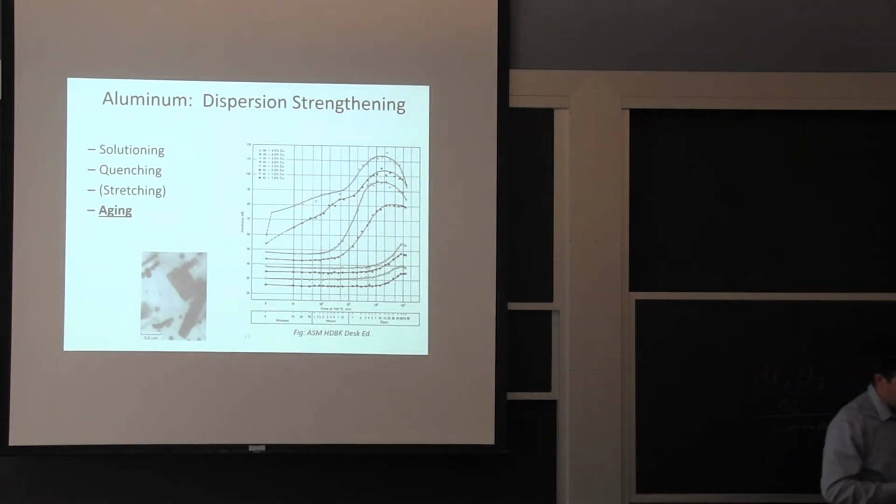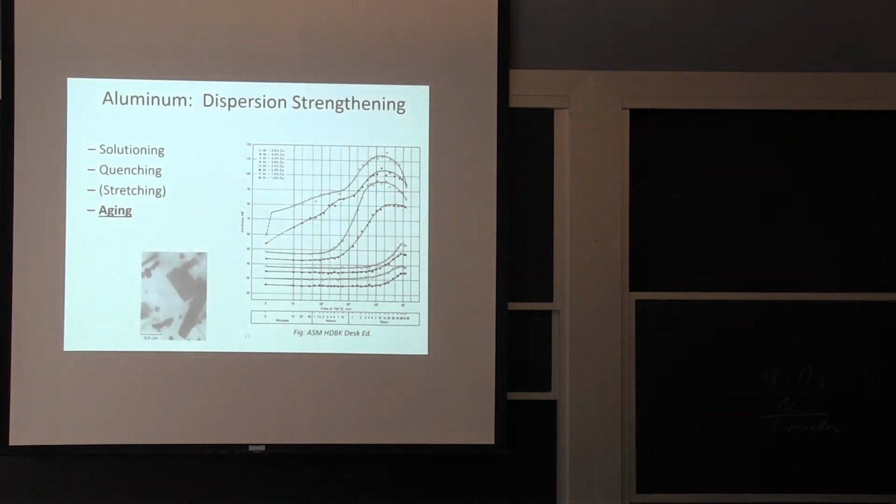So this concept is used with stainless steels. You have a lot, because stainless steels tend to be soft because they are that austenite. That's the high temperature phase. It's very deformable. So you can create different kinds of precipitates in the same way that you do with the aluminum, and that's used for fasteners, for example, quite a bit. Because you do want their strength. And you form them to the geometry exactly you want, then you heat it up. The same way when we were talking about the aluminum fuselage, you make the shape you want and you heat it up, all of a sudden it's becoming super strong, and that's ready for service.